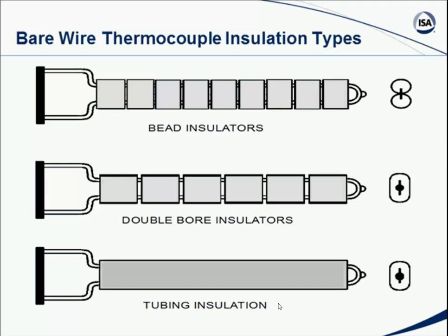Again, thermocouples are made from wire, so they're mechanically a bit stronger than an RTD would be, and we have to deal with the temperature characteristics and rigidity characteristics and expansion characteristics of the metals used. That's actually one of the reasons quite often you'll see there are gaps in the insulator beads, because as the temperature goes up and down, the wires themselves will expand and contract a bit, and we have to allow for that in the design of the thermocouple.